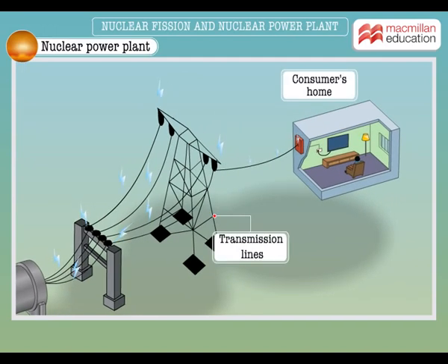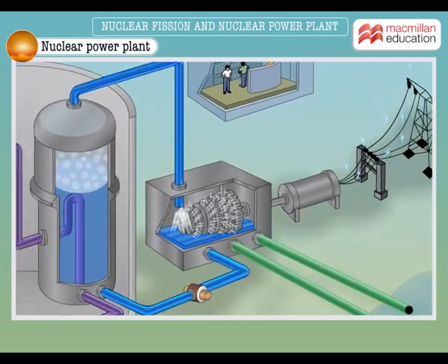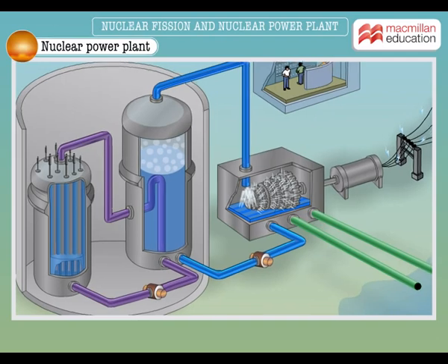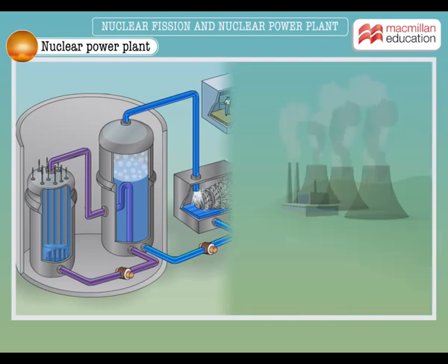Now, for the last part, let's zoom back to the steam generator and turbine region. Observe that the turbine is connected to a steam condenser at the bottom. The spent steam after turning the turbines is cooled by the coolant water that is pumped from a water source such as the ocean. Steam condenses into water on cooling and collects in the condenser at the bottom.